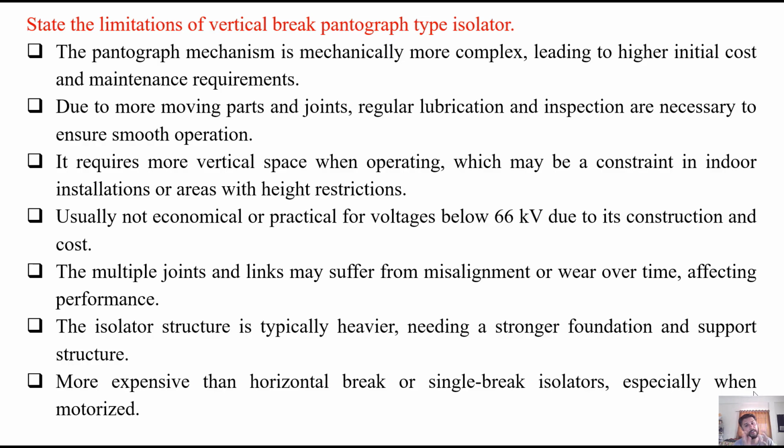So there are several advantages as well as some disadvantages of this type of isolator. The pantograph mechanism is mechanically more complex, leading to higher initial cost and maintenance requirements. Due to the more moving parts and joints, regular lubrication and inspection are necessary to ensure smooth operation. It requires more vertical space when operating, which may be a constraint in indoor installations or areas with height restrictions.